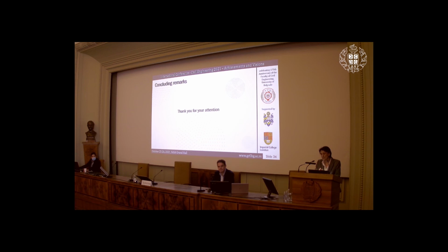If you think that we may have maybe 30, 40 triaxial tests performed on a site, then that would really cause quite a bit of skewness in the data if we just try to look at average value, purely statistically, just find average, mean, and so on. So what we tend to rely on is, at the moment, not really statistical unless we have a large quantity of data. That is the issue.